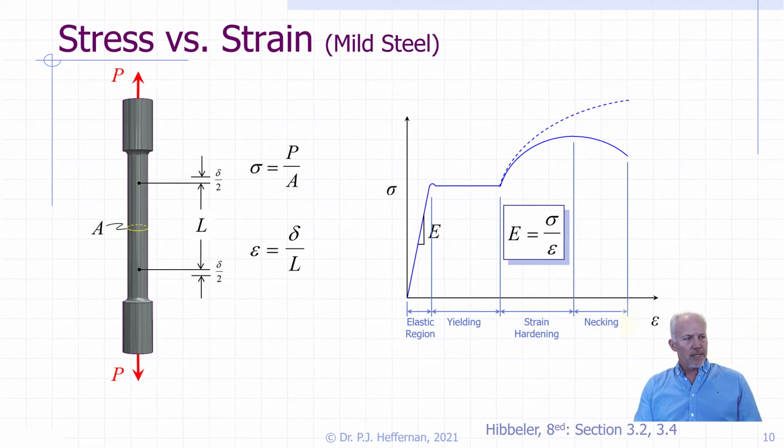Likewise, when it comes to the elongation, there are a number of ways that we can do this. We could do this with an extensometer, where the points of the extensometer move, and because of the geometry of the extensometer, we know the displacement.